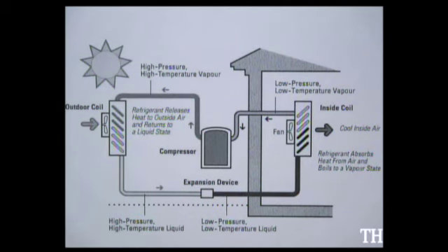Now, when it leaves the condenser, its temperature is much cooler. Once this high pressure, high temperature gas enters the outdoor coil, the condensing unit, and the aluminum fins dissipate this heat, it changes from a gas to a liquid state again, lowering the temperature.